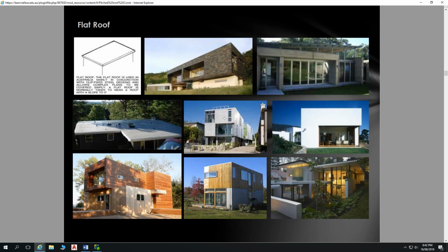Also, there are flat roofs. Now, no roof is entirely flat. All roofs have to have some slope on them. So a flat roof might only be 1 or 2 degrees pitch, but we have to get that moisture off the roof and into the roof plumbing somehow, into our gutters and downpipes, etc. So those roofs are typically created through the use of products called metal decking, which are flat pad metal sheeting with a high expressed rib profile.